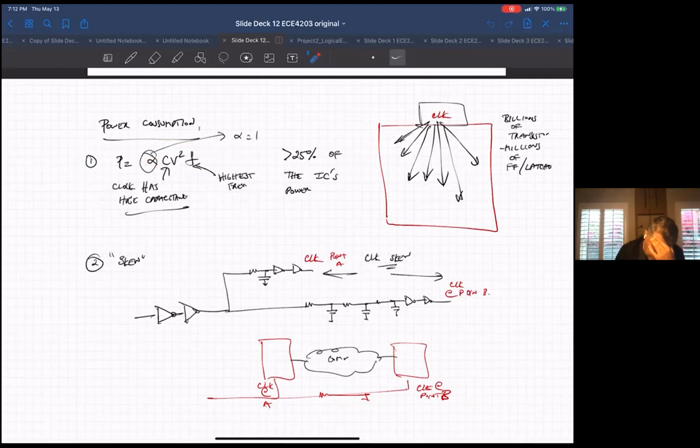The second thing that gets really important is the concept of skew. There's this concept of, I don't know what they call it, maybe the theoretical clock. When you're designing your Verilog code, say, you have a clock. Correct me if I'm wrong, I don't know what you've played with in terms of these HDL languages and design logic. You have a clock that goes to all your circuits. Maybe it's a notional clock or a theoretical clock, where it arrives at all your flip-flops or latches